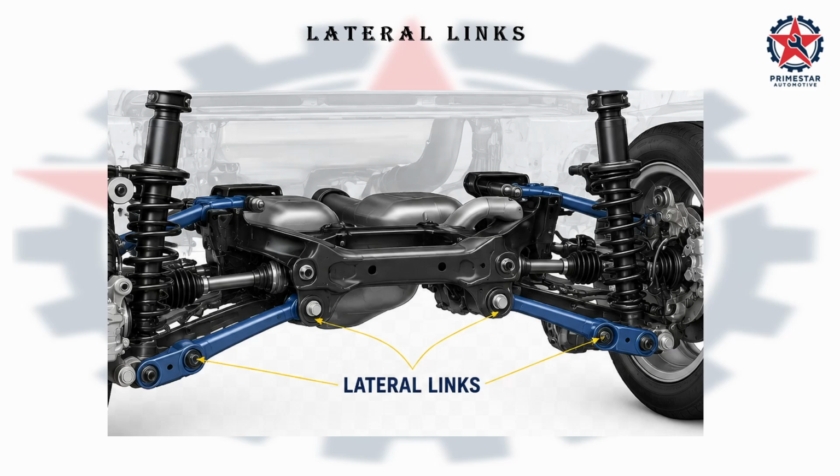This closer view confirms where the lateral links are fitted. Notice how each link extends from the rear subframe towards the wheel hub or hub carrier. Because this is an independent rear suspension, each wheel uses its own links and can move separately from the wheel on the opposite side.